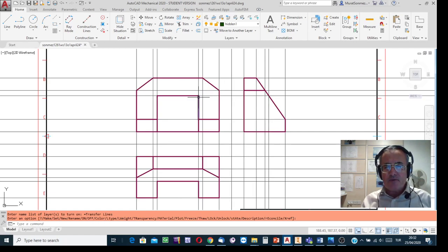If the abscissa for the front view of point A is equal to, for instance, a certain number of millimeters relative to the origin of the coordinate system, then its top side view must use the same abscissa value. Creating such a transfer line, we guarantee that the images of the object are consistent with each other.